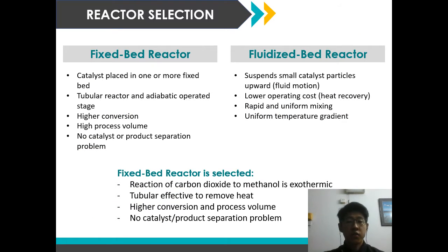For reactor selection, we have compared between two reactors, fixed bed and fluidized bed. Fixed bed having a higher conversion, whereas fluidized bed having a better heat recovery. But due to the chemical reaction of CO2 to methanol, that is exothermic, we have decided that fixed bed reactor should be selected, and also because of the reasons as stated.